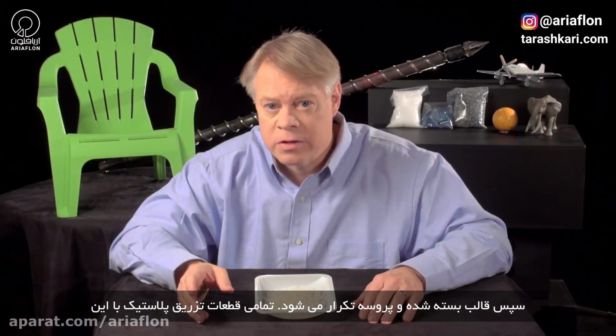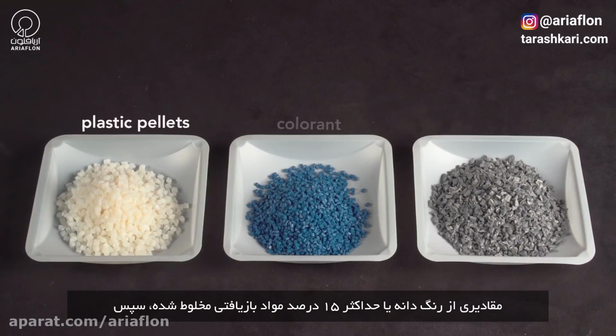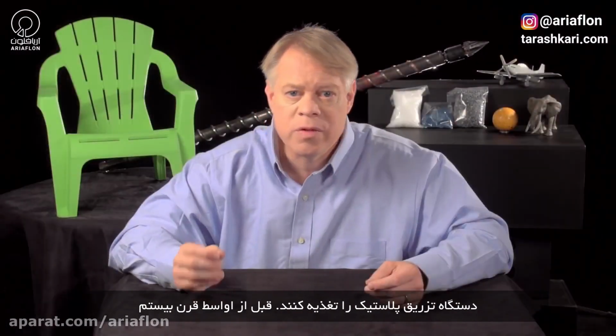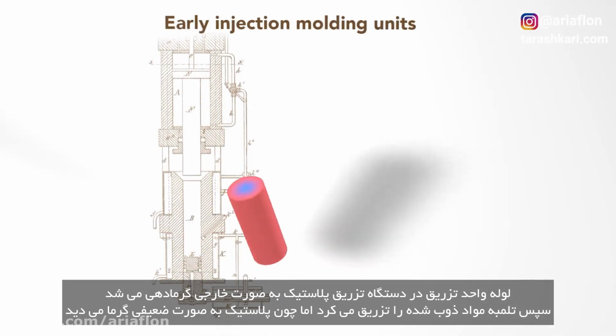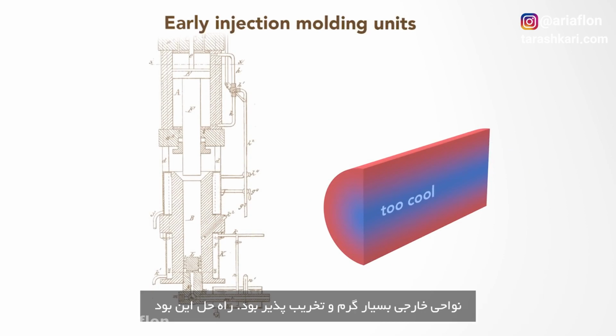All injection molded objects start with these plastic pellets, which are a few millimeters in diameter. They can be mixed with small amounts of pigment called colorant, or with up to 15% recycled material, then fed into the injection molding machine. Before the mid-20th century, injection molding machines used only external heating of the barrel to melt the plastic before a plunger injected the molten material. But because plastic conducts heat poorly, the temperature was uneven in the barrel. Either the middle was too cool and not fully melted, or the outer regions were too hot and degraded the plastic.